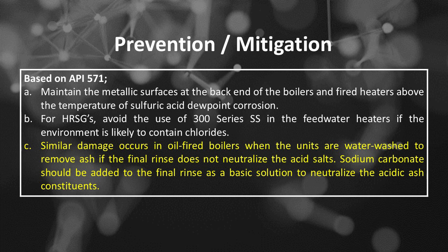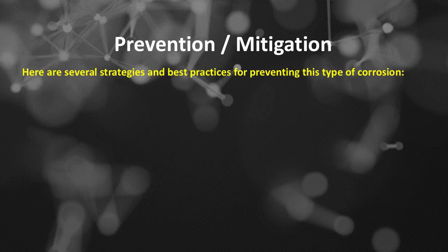Similar damage occurs in oil-fired boilers when the units are water-washed to remove ash if the final rinse does not neutralize the acid salts. Sodium carbonate should be added to the final rinse as a basic solution to neutralize the acidic ash constituents. Here are several strategies and best practices for preventing this type of corrosion.